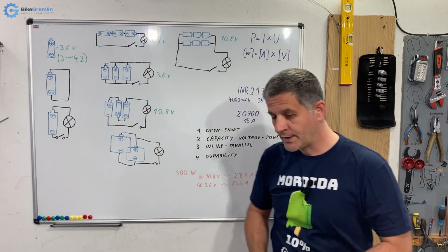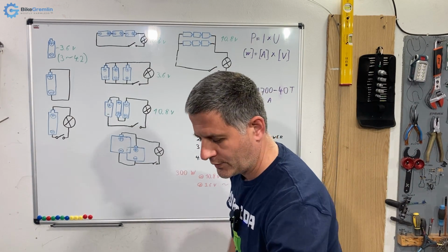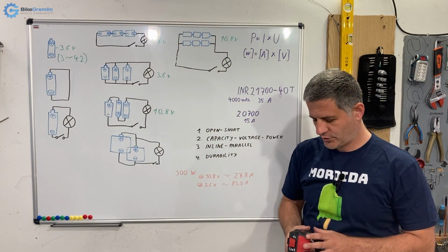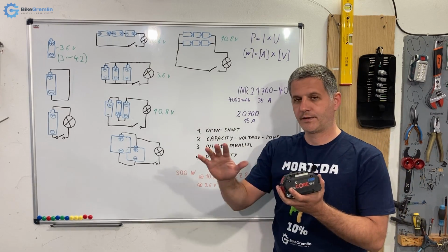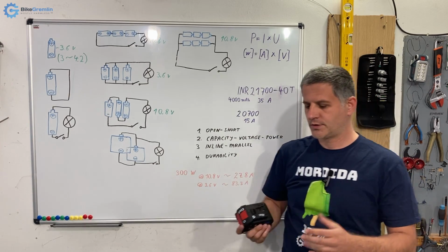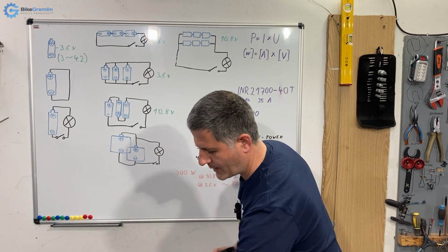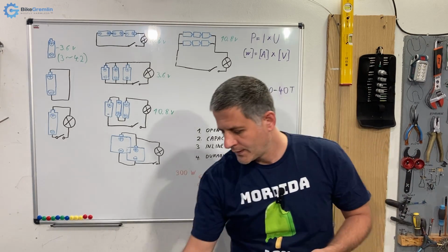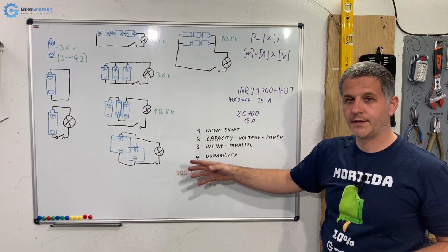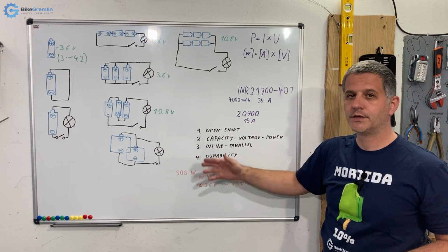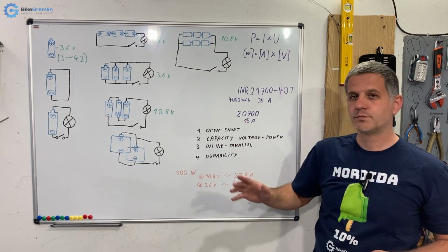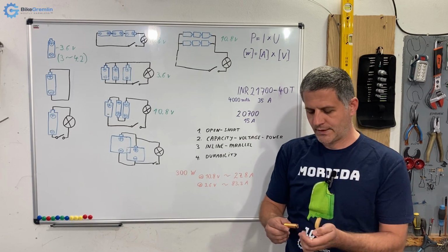So that's the catch. Also, when we talk about higher capacity, more powerful, stronger tools, they are usually packed with 5 batteries in line instead of just 3. That's not done for smaller tools because you physically need to pack so many cells. For powerful tools it's necessary because you need more power, and to get more power you need either higher voltage or more amperes, and there is a limit of how many amperes you can get. So most manufacturers today are using 5 battery cells in line.